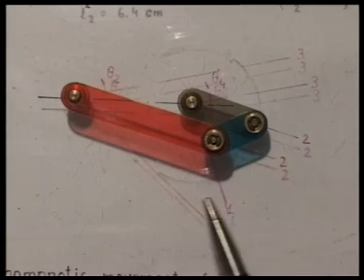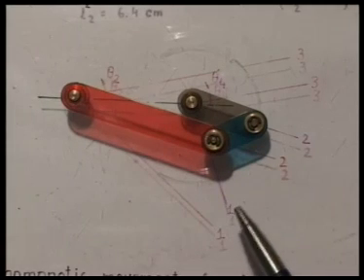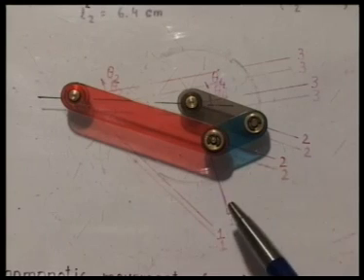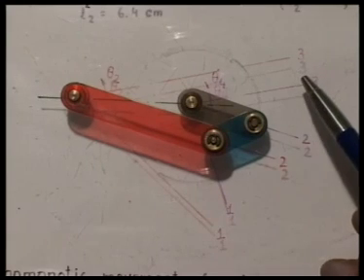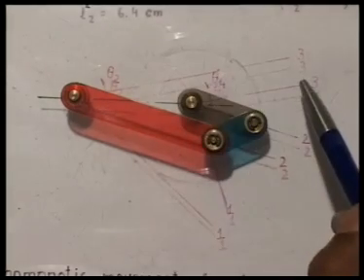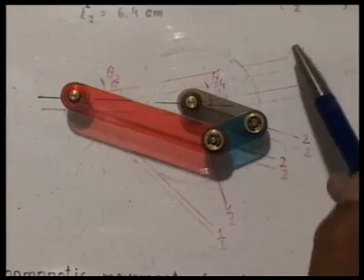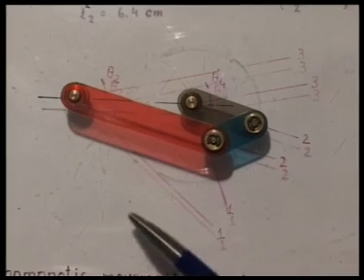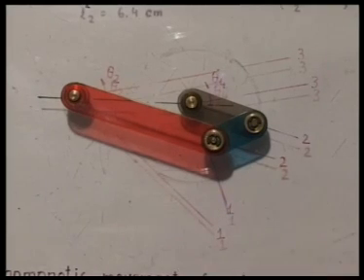So, what we see, there is a non-monotonic movement. These positions 1, 2 and 3 are not taking up in the serial order. If we take up 1 and 2, then 3 is taking up during the return stroke, and if we take up the third configuration, then in the same stroke 2 and 1 are not being taken up, 1 and 2 are being taken up during the return stroke. This is not a branch defect, but this is some kind of a non-monotonic movement.